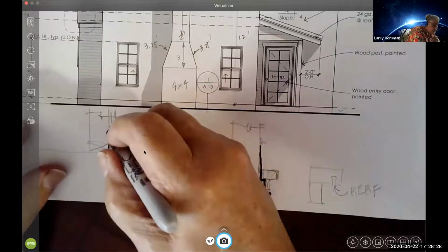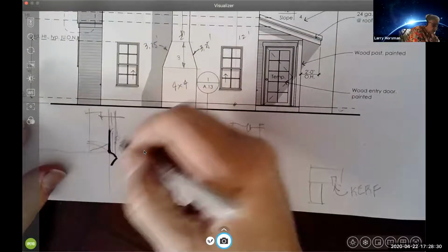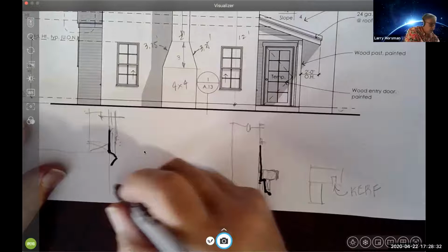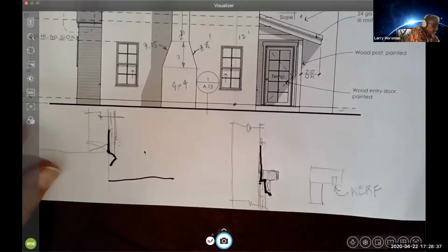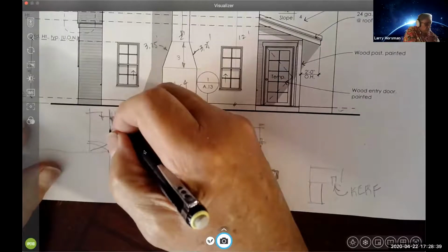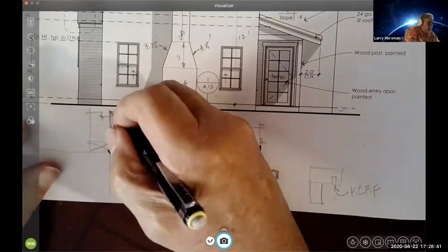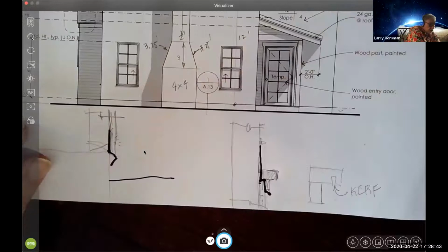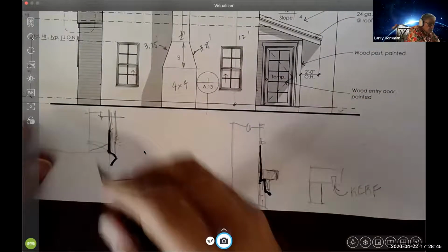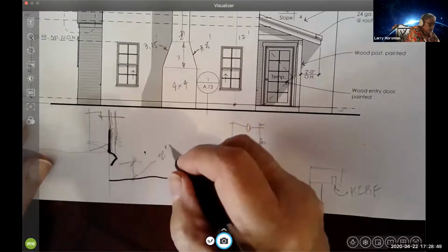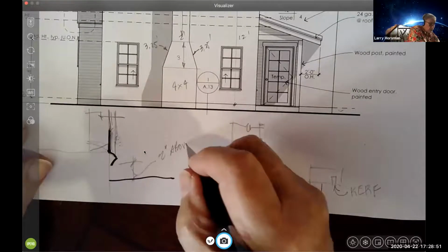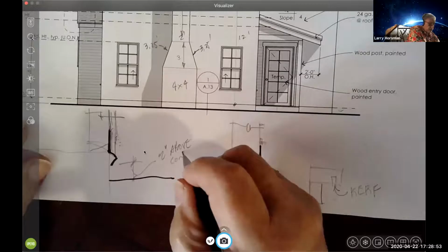This has holes in it. Yeah. So the paper laps over the screed. Paper comes down over the flange on the screed. This is 2 inches above concrete or 4 inches above dirt minimum.